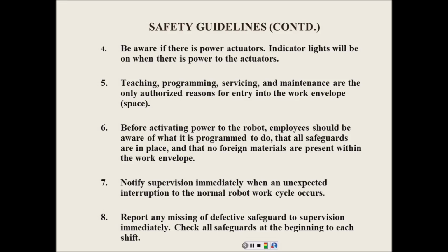So what we do is we park the robot at their point of origin. We can't afford to keep all these spare batteries and everything around here. They're very expensive. So we park the robot at their point of origin. And if the power fails, then we can come back and remaster the robot. We'll show you how to do that. Y'all won't do it, but you'll be able to do it in the industrial. We'll recalibrate the robot because it's parked at its origin, and then you'll be able to take off from there.